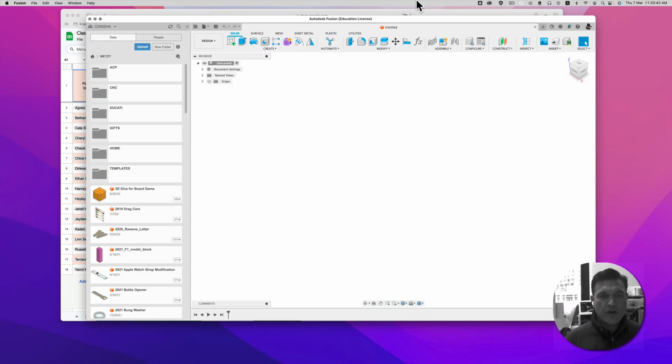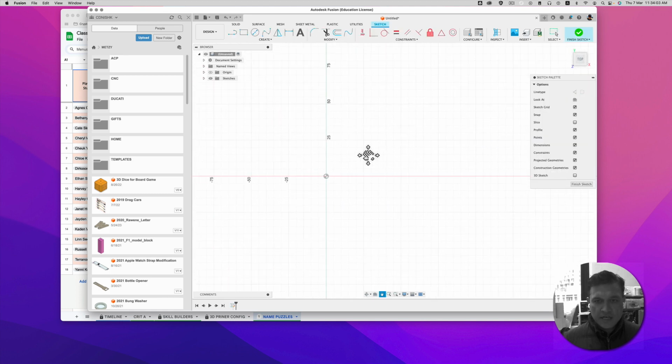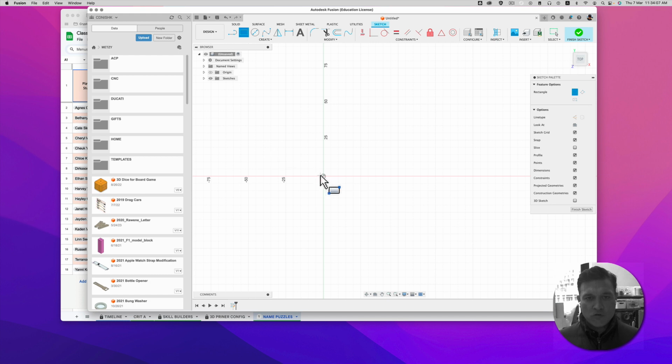Okay, in this video we're going to learn how to create a simple name puzzle that will ultimately be manufactured with the laser cutter as well as the CNC machine. We're going to base this on a new sketch. I'm going to sketch on the XY plane, and with a rectangle sketch tool I'm going to create a rectangle that is 100 by 300.